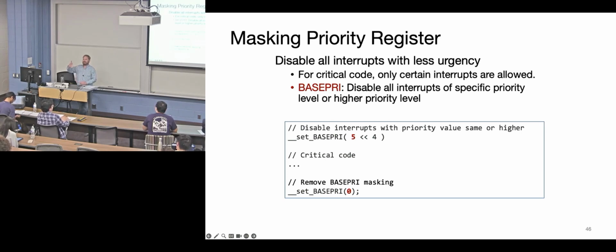Right, and so by dynamically programming the value of this register in your main function, you would say, I want to do this or not do this. Or you could, in some other interrupt, say, okay, this one's so critical, I want to set everything else high so I don't get interrupted out of this. So this can be just a function, not an interrupt, right? Correct, absolutely. This is just a register. You just put data right in that register whenever you want.